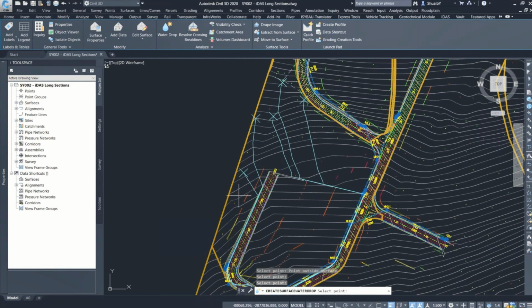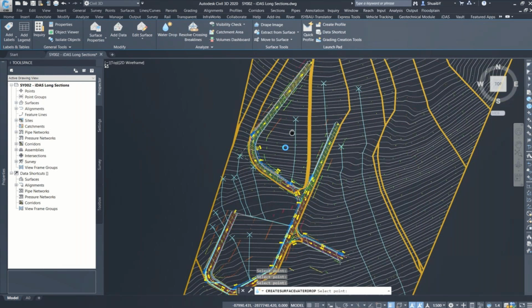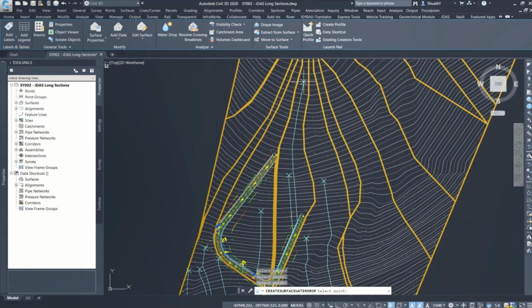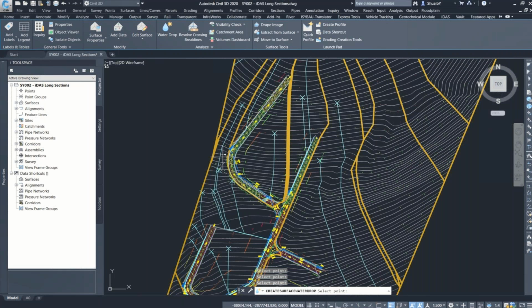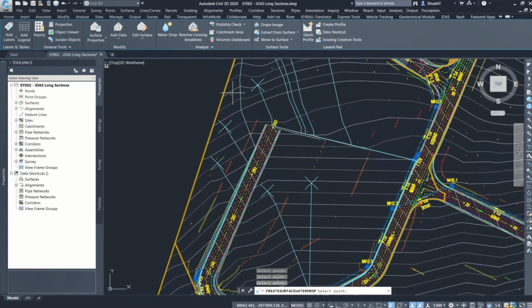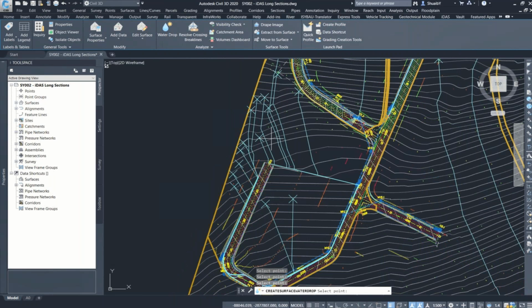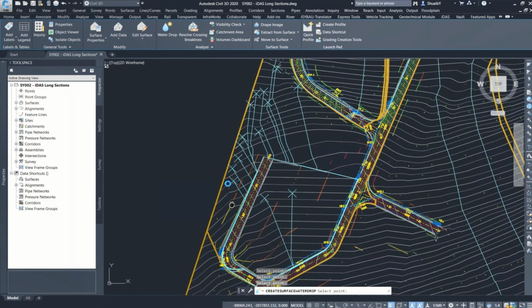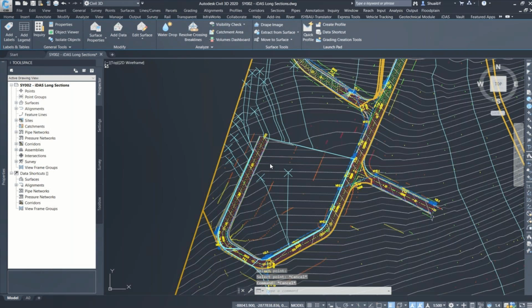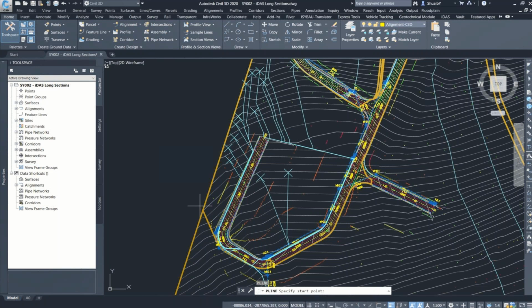You can go crazy. What we normally do is we just click a bit wildly, but if you have a really good solid design, you know more or less where to click for critical areas. And as you can see, it's giving me the places where the water is actually flowing away from my road, which I don't really need to worry about. It's showing me the longest flow path. So you can use this to generate your flow paths rather than doing a polyline in Google Earth and getting the measurement of it. Or you can even plot it in here, which I'm going to be doing for this demonstration because a lot of people have that understanding. So as you can see, my road's designed pretty good where the water is going to be gravitating towards the channels and then moving to the inlets at a certain position. So I'm going to draw a polyline for the curb inlet on the left hand side.